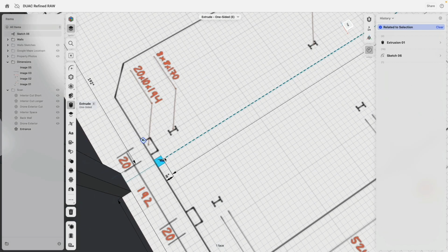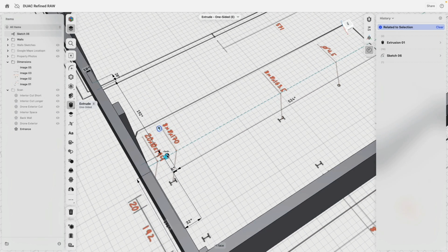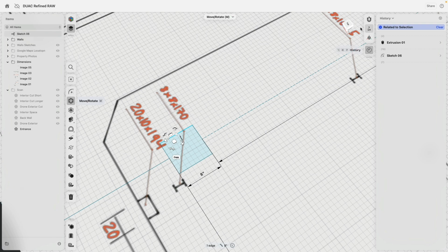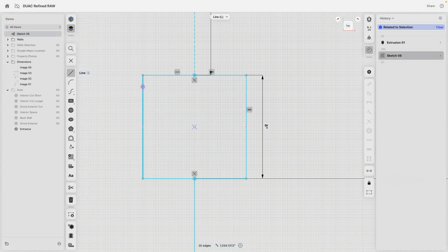Now, this has an extrusion height of 170. Before I actually extrude this, I am going to sketch in very quickly the outline of our frame. So I will go back to editing this sketch. Then I will draw here a horizontal line, escape, another horizontal line, escape, a midline, escape, a right line, and a left line.